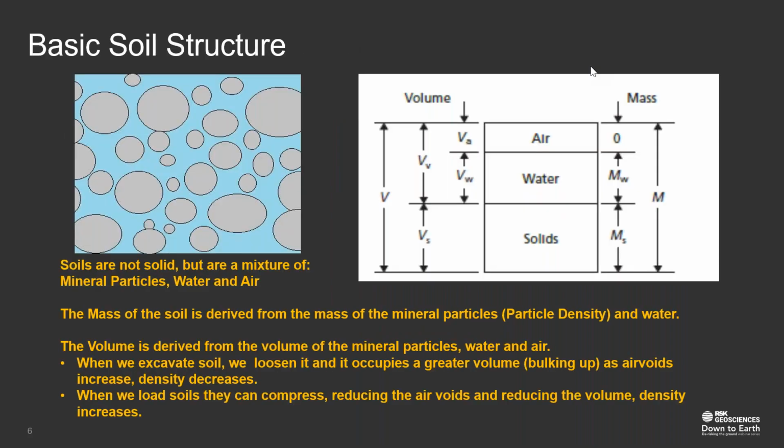First of all, a bit of soil theory. Soil is a mixture. It's not a solid. It's a mixture of soil particles with voids in between them. And these gaps are filled with a mixture of water and air in varying proportions depending upon the soil and how dry it is. When we excavate a soil, we loosen it, we increase these voids, and generally we increase the amount of air within the soil.